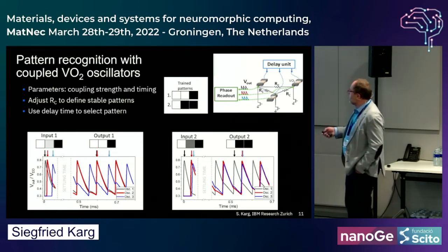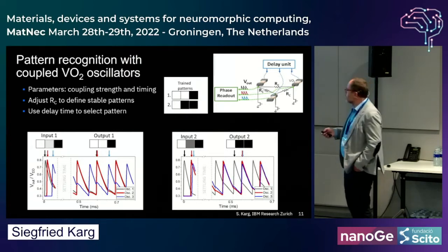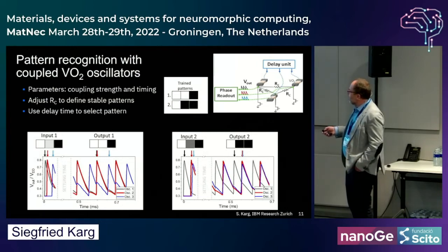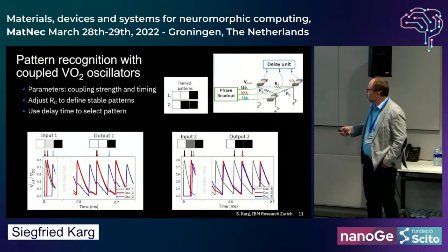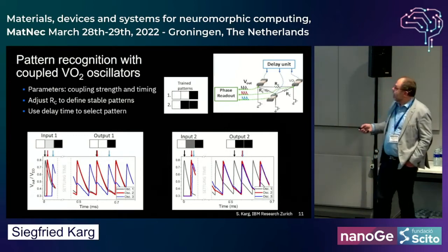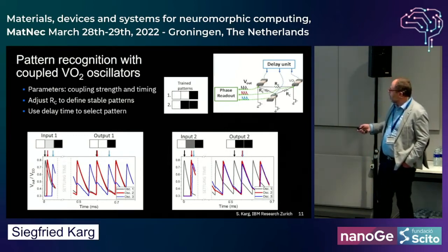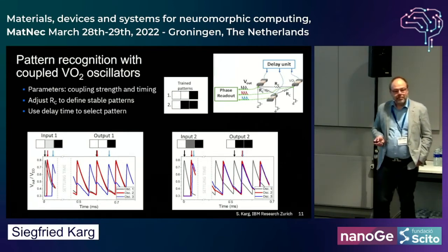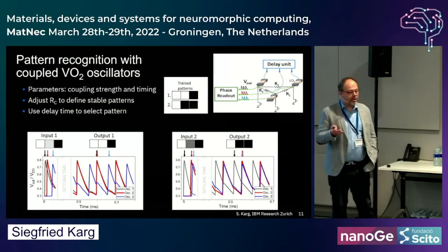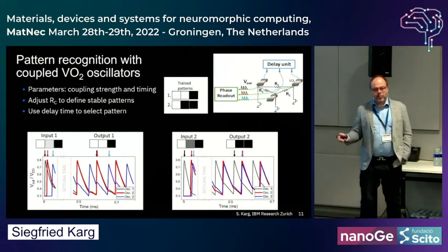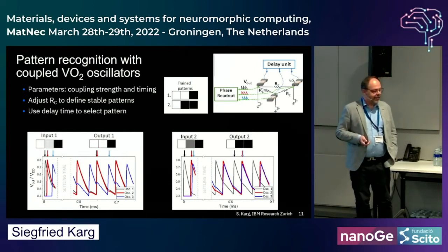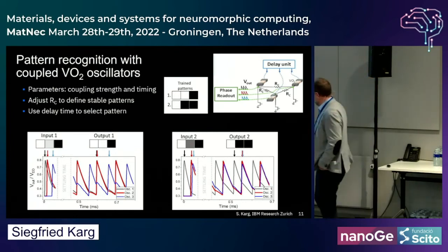If we use the same circuitry, same coupling resistance, but just vary the timing, the input, so we input now a dark gray, meaning that our second pixel has a time delay which is closer to tau or a half. Then after a couple of oscillations, the middle pixel and the right pixel will go in sync. So that's our first experimental pattern recognition. We have an input which is a gray pixel image, and the output is one of the 2 trained states.